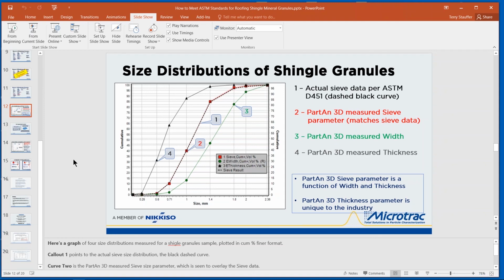There are many types of splitters. It's the only sure way to know that you're going to be measuring a representative sample. And I can tell you that a rotary splitter is the best splitter to use. And you can find those on various websites like Gilson and other suppliers of equipment for splitting samples.